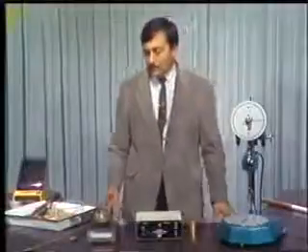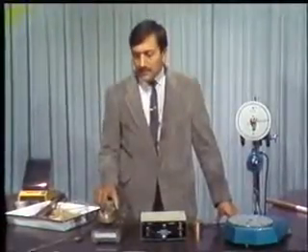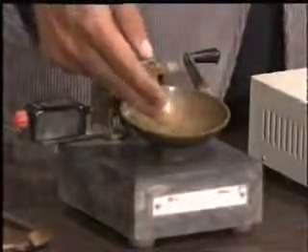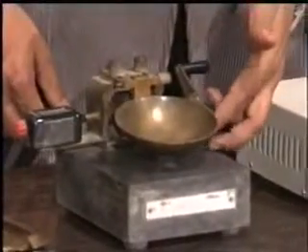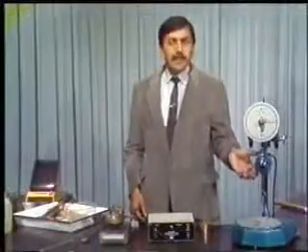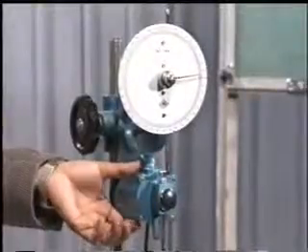Using an automatic timer reduces the chances of human error. Further, in the other method, the accuracy is largely dependent on many factors, which includes the accurate filling, the accurate cutting of the groove, and the accuracy in the height of fall, whereas this method is comparatively free of the procedural errors.